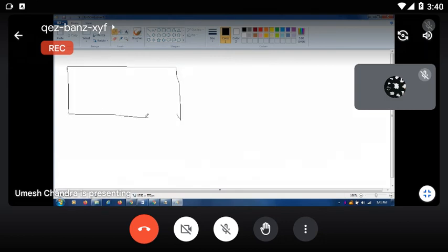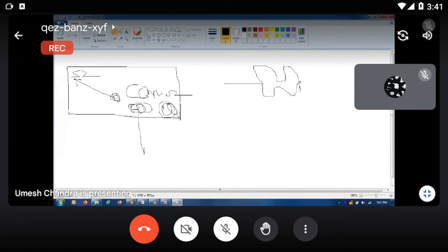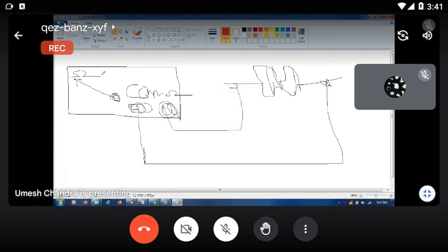Now this is the multimeter. It has the COM common point, and this is the ohm point, and here is your rotary switch. Just rotate this and select the ohm range, and here is the black one. This is the resistor. You can connect either terminal to either side. The black probe goes to common. Then you see the display, how much resistance value. Let's suppose 1100 ohm. You measure like this.